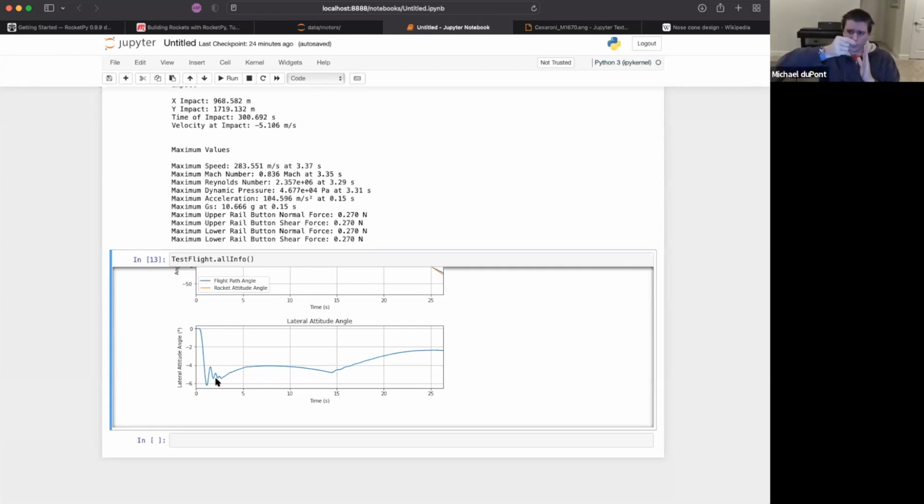And when the first rail button, or eye hook, or whatever you're using, comes off of the actual rail that it was sliding on, well, now it wants to try to turn, because this is now free, but the bottom rail button is still on the rail.